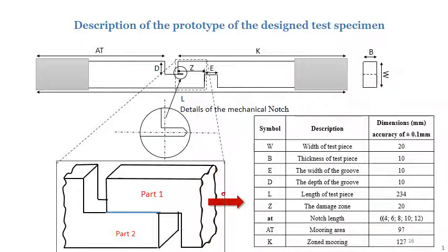In order to highlight the plane shear on a wooden specimen that we want to be easy to achieve and reproducible, we consulted a series of publications dealing with this phenomenon, as well as the experimental devices developed in our laboratory. We have chosen a specimen inspired by the shear test according to the standard NFB 51012. After several attempts and by taking inspiration from the various devices, we were led to choose the geometry which, according to our study, will give better results.